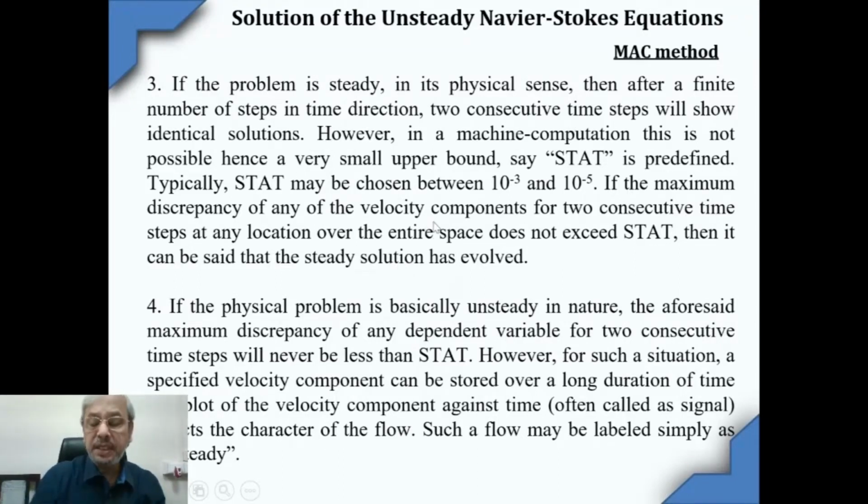That means at each location, whatever values we get, at the same locations the values that we get in the subsequent time step are the same, and if there is any difference, that difference is less than a predefined value, which may be 10 to the power minus 4 or 10 to the power minus 5.